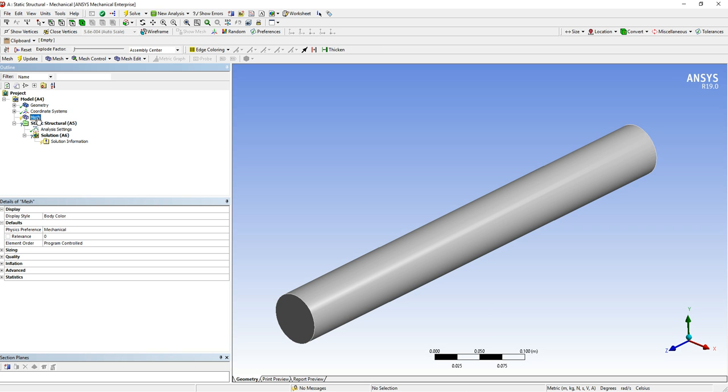Normally when I run these simulations, I don't try to do the most sophisticated thing in the world straight away. I get the basic, bog standard, quite poor thing running, and then I'll refine and refine and refine. Just because personally I'm never that confident to go, yep, I am that amazing, look at what I've done. So when it comes to the mesh, you'll notice that there is a lightning bolt. This is essentially saying I do have something I can use. It's a basic one. So I've right clicked on mesh and I'm going to go generate mesh.